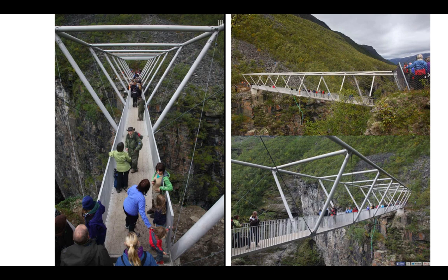So notice that the cross bracing is all in tension cables. The verticals are what we would think of as compression chords. Those are all in cylindrical pipes. And notice too that the connections, everything that's done in the factory, is very, very tight. The connections to the mountain itself are relatively crude, right? It sits on a couple of relatively bulky concrete foundations. So minimizing the amount of on-site work that needs to be done.